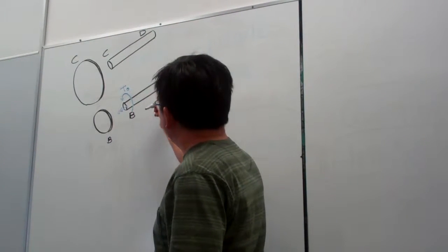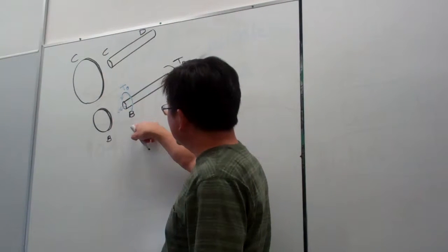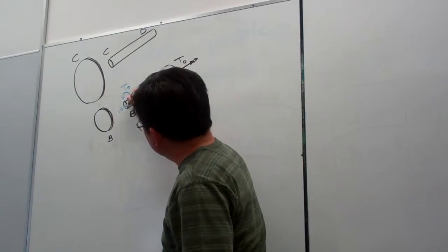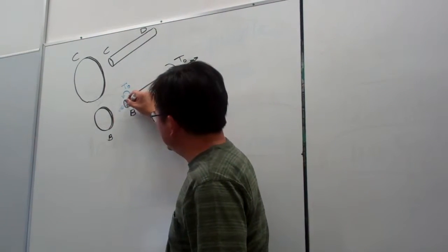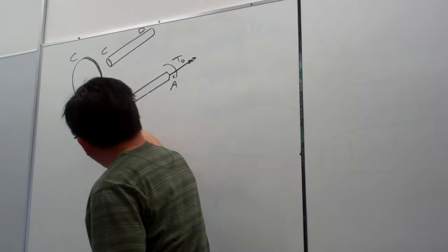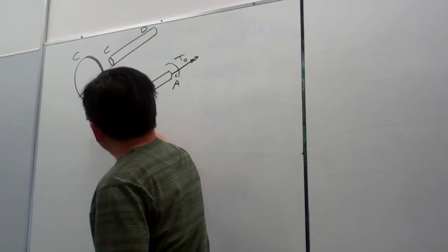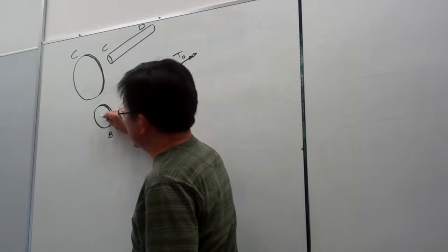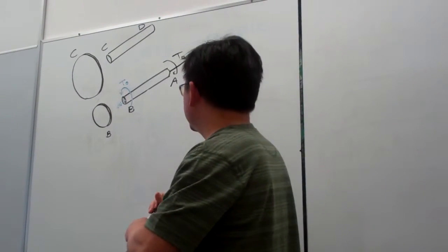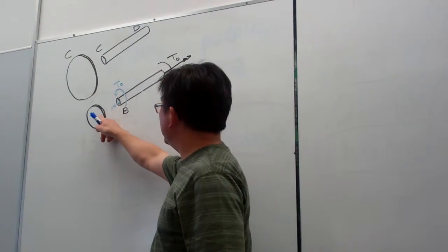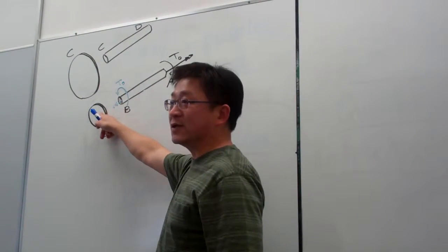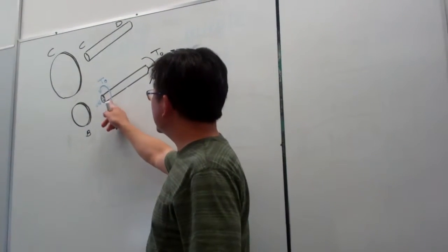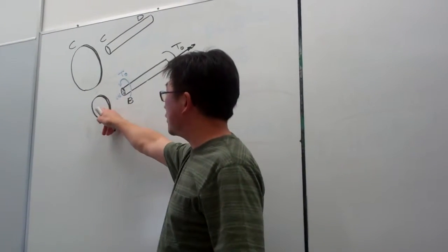Okay, so now we've done the free body diagram for this part. Now you can see, assuming we weld the shaft along the perimeter at this end, suppose here has some holes on the gears, but anyhow we assume this end is welded to the gear, so they have a rigid connection. So that means the torque T here and this one are an action-reaction pair. Whatever reaction develops at this end B will directly go to the gear here.